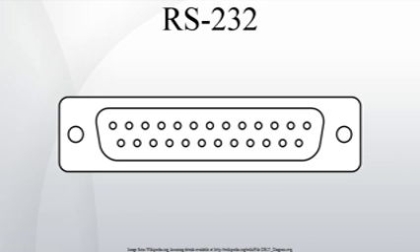Related standards. Other serial signaling standards may not interoperate with standard compliant RS-232 ports. For example, using the TTL levels of near +5 and 0V puts the mark level in the undefined area of the standard. Such levels are sometimes used with NMEA 0183 compliant GPS receivers and depth finders.